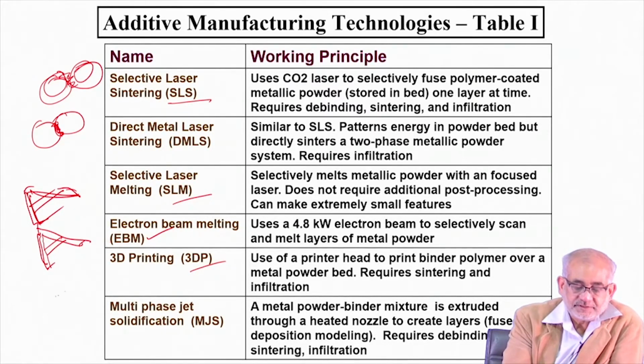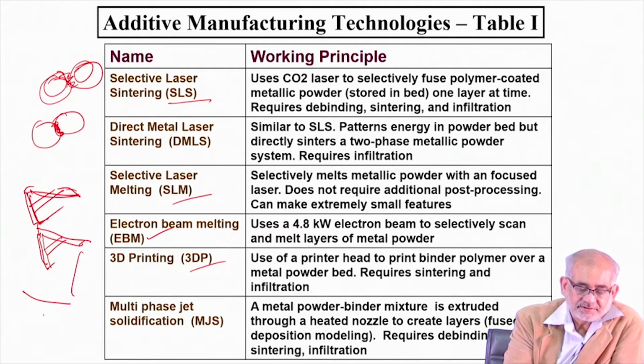Now, usually the powder feed and the laser can be different, coming from different directions, but in principle, or in reality even, it's also possible that you have a laser beam coming through a particular nozzle, and you have a concentric feeder or hopper around it, which can feed one single or multiple powders.